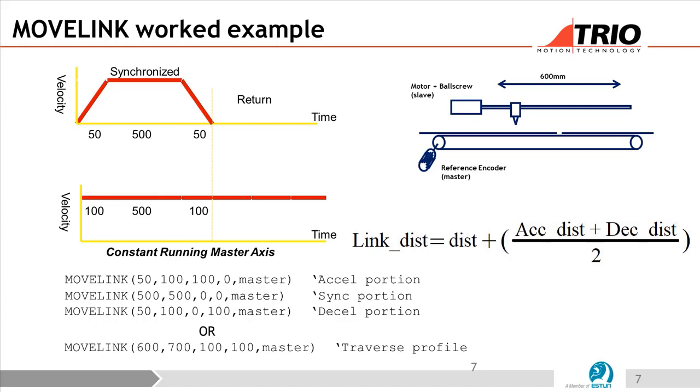And the acceleration and deceleration always have to be the same? No, they can be different. Okay. They can be different. So the only rule is that there's this 2-to-1 ratio. So what you can't have is to say, well, I want it to decelerate over 100, but I want the slave to also be 100. So as long as it's the 2-to-1 rule, then any will do. That's probably the reason why they are different parameters, so you can have them separated if you want.